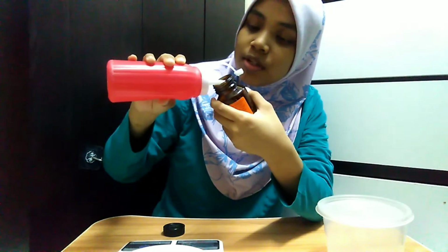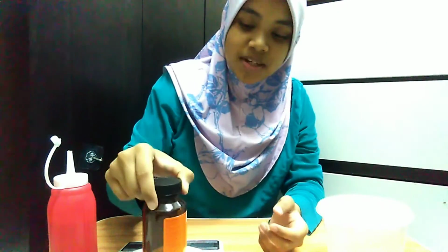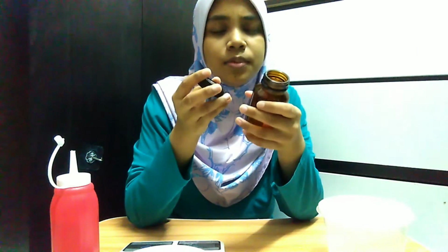We empty and clean the density bottle and stopper. Fill it with distilled water until the bottle is full. Put the stopper on and take the mass. Again, we empty and clean the density bottle and repeat the same method for sample number 2 and number 3.